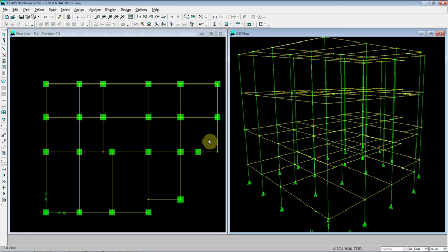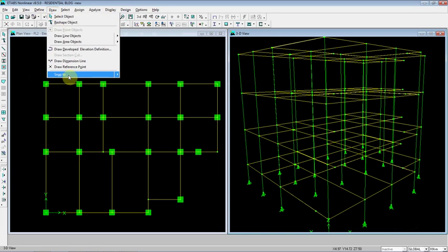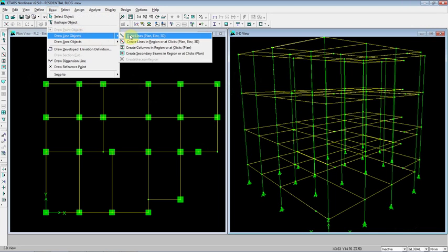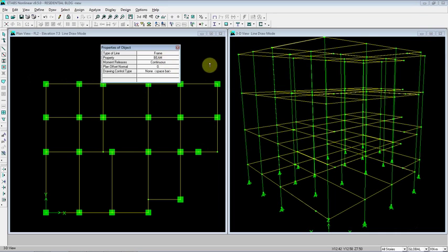Once the dead loads have been assigned, we move toward the staircase loads. For making that, we need an additional landing beam in between the floors. To make the landing beam, go to Draw, Snap to Midpoints. Again Draw lines. We choose the property of section and make beams.